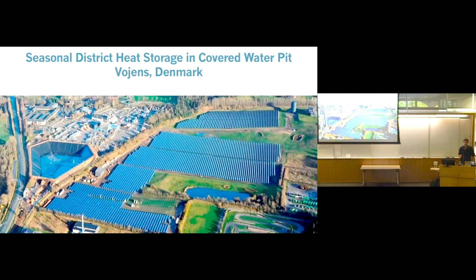So it conserves the temperature when it's underground, so you can adjust based on whether you need heating or cooling. You have to have them far enough apart, because you're going to have diffusion of heat. Even in the aquifer, I mean, it's water, so you do have some diffusion of the heat, but it's relatively slow. And so I think you could do it in soil. Not with the water pit storage, it's not as easy. But ice storage is definitely a cooling storage system. Now with underground borehole storage, you could do two sides where it's cold and hot. But I haven't heard of any cold storage in soil, just in aquifers.